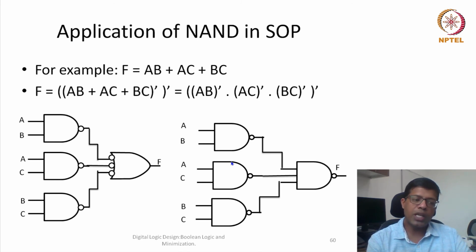Here also the same logic applies. The basic idea of implementing all the sum of product expressions using NAND gates is that we can have a generic implementation. That's the reason we can always go for sum of product expressions, so that if we have a configurable chip with two arrays of NAND gates, then these two arrays of NAND gates can be utilized to design any kind of configurable circuit. We'll discuss the details of how that circuit would be designed some time later in some other modules.